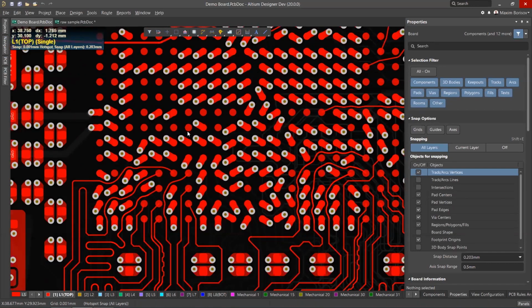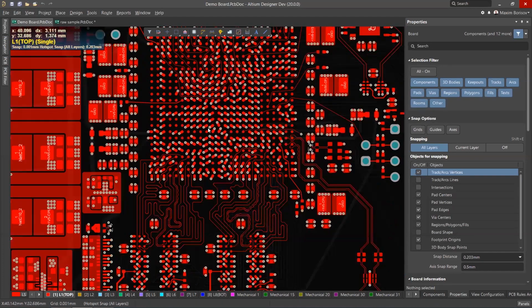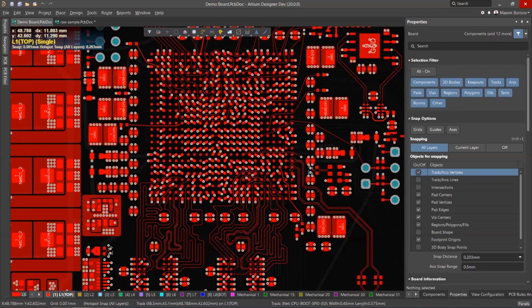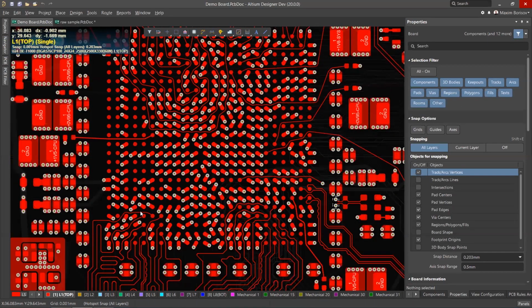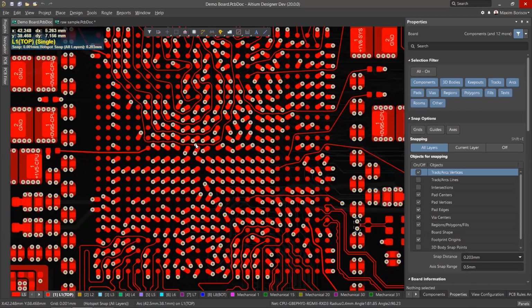While with this technique, you're able to route probably in all directions, even from the very center, and even from the upper left corner to the very left corner. And in practical terms, most probably with 90% probability it will give you a severe reduction in layer count. For example, this particular CPU is usually routed on 10 layers, but here we have 8 layers. And it's only this routing, but this is not all.